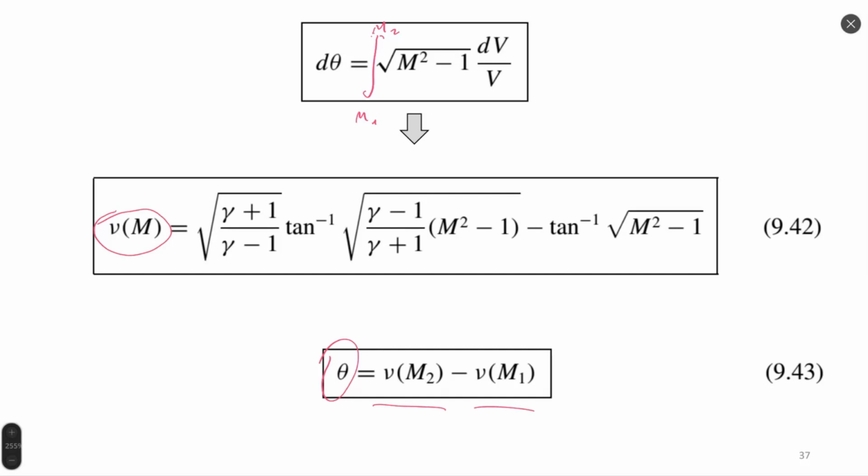It requires just the adiabatic constant gamma, and also requires the Mach number as a parameter. There are no other parameters inside such a function. Gamma is constant. I would like to remind you that for air, gamma is equal to 1.4, corresponding to the physical properties of air.